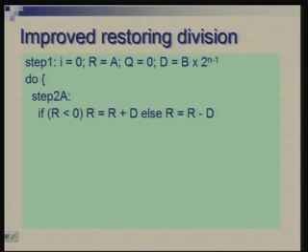Okay. So, the algorithm now looks like this: initially we look at the sign of r, okay, because possibly there might be a pending restoration requirement. In the previous iteration we might have subtracted where subtraction was not to be done, and as a result we may have a negative r value.